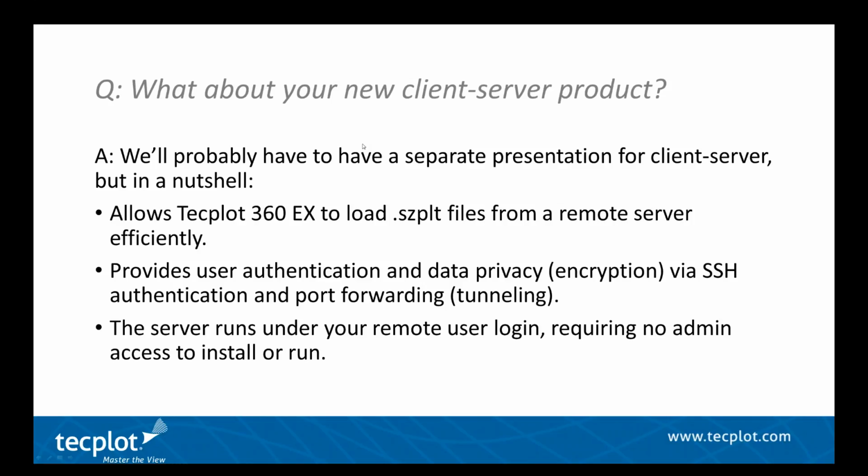So you could, for instance, with the server, have a version of Tecplot out on the server end that you could use to convert whatever file format you have to SCPLT for use with the server. And you don't have to have a licensed server. It'll run unlicensed, provided you use the convert flag. Let's see what the next question is.